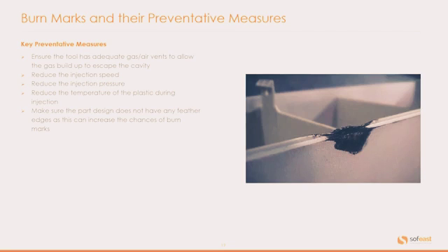Some key preventative measures to avoid burn marks. Ensure the tool has adequate gas and air vents to allow the gas buildup to escape the cavity.